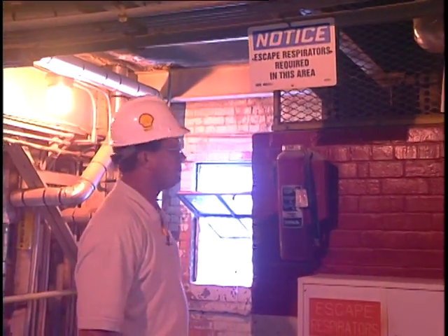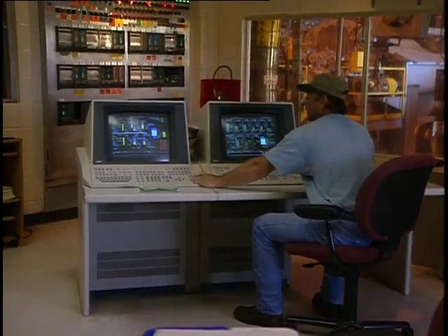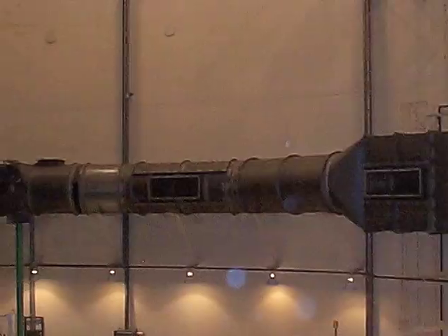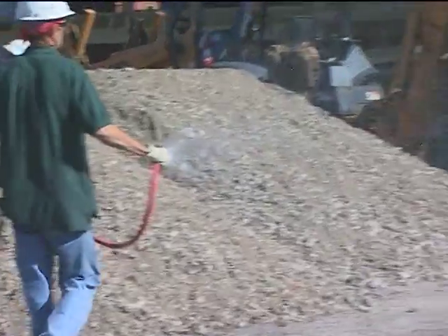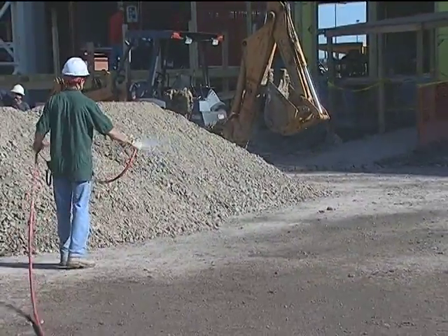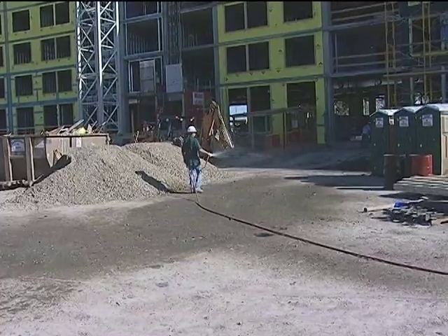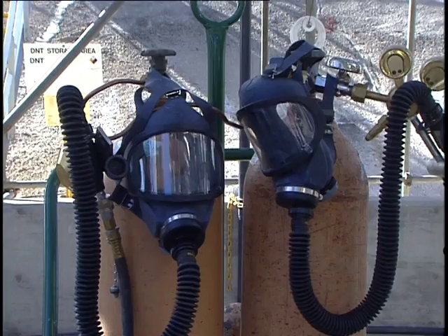Atmospheric control should be accomplished as much as possible by accepted engineering and administrative control measures, such as confining the work operation, installing ventilation systems, using water sprays and/or substitution of less toxic materials. These types of controls are generally regarded as the most effective methods to control exposure. When effective control measures are not feasible or while they are being instituted, appropriate respirators must be used.